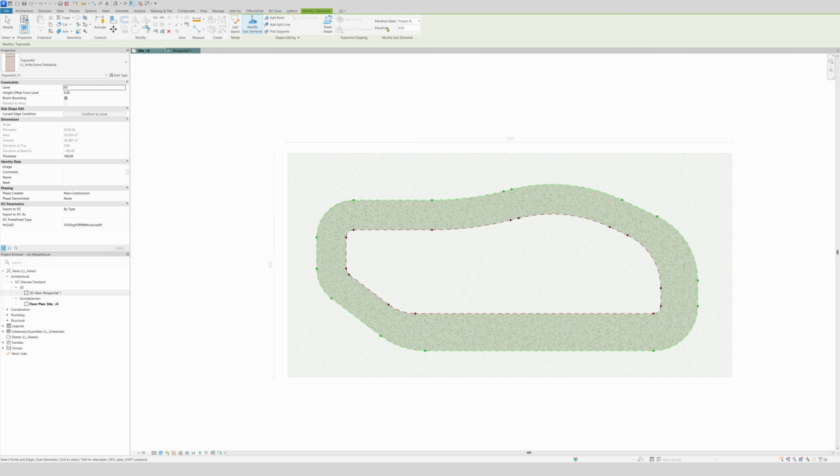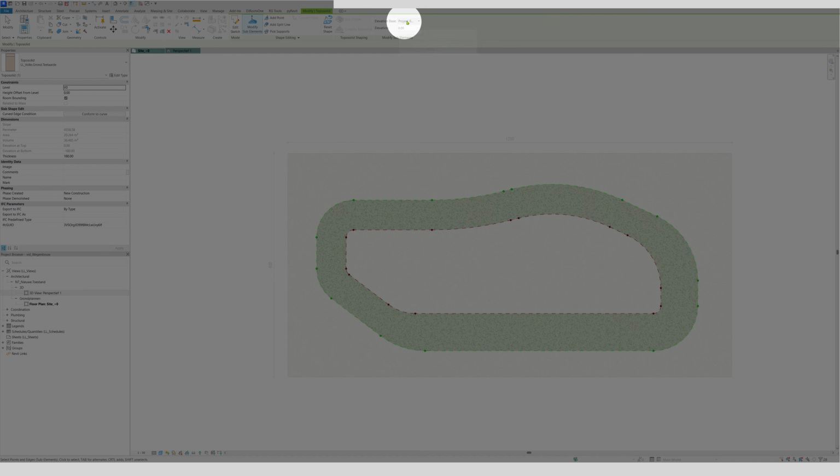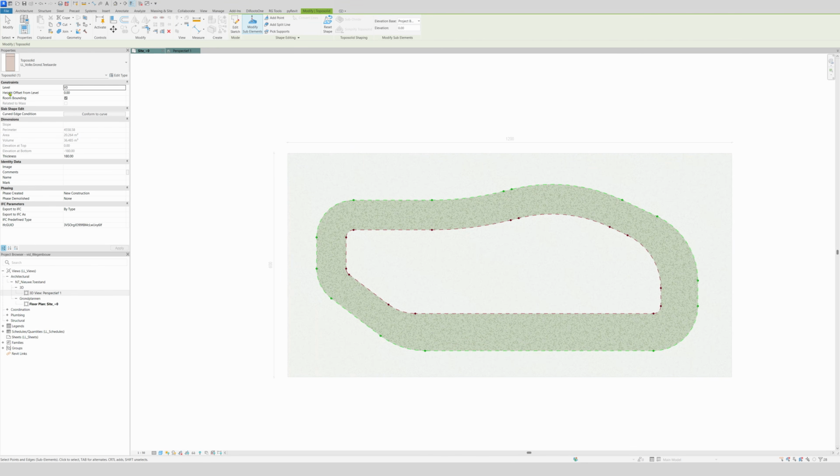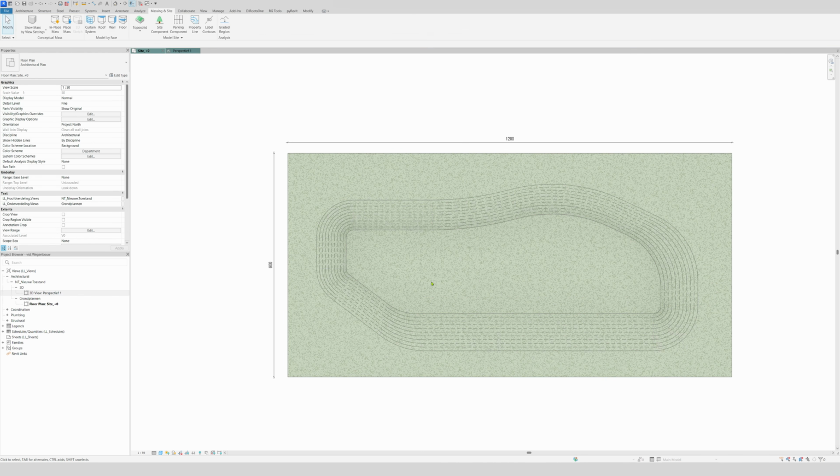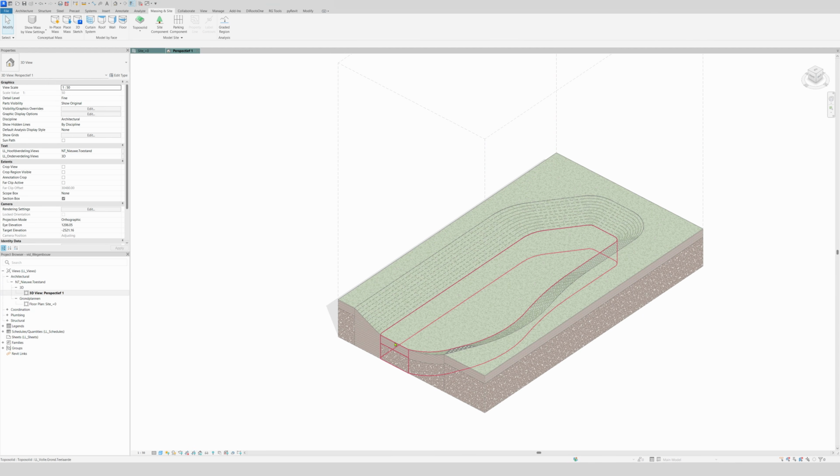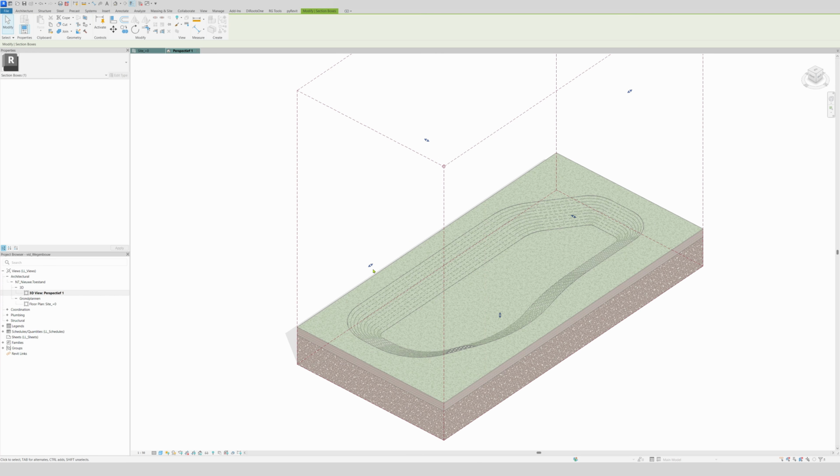And now right here it sets the elevation, and the elevation is our project base point, so where our level is. Floor now 0, so we're going to do -50. Why -50? Because you will remember in this perspective this is 50, so that's what we get. So I will change it, voila.